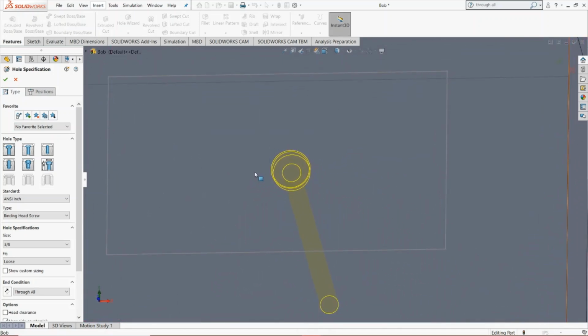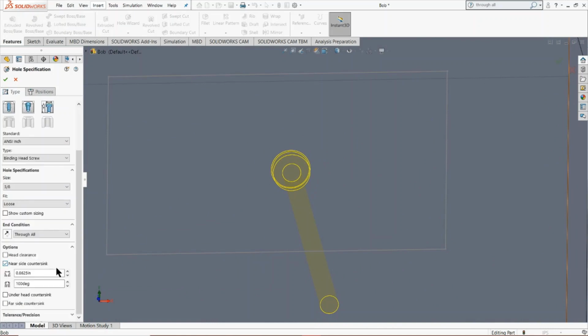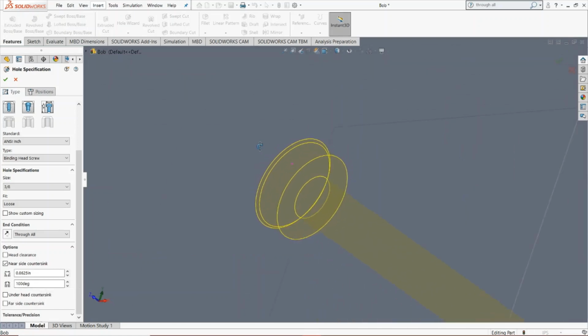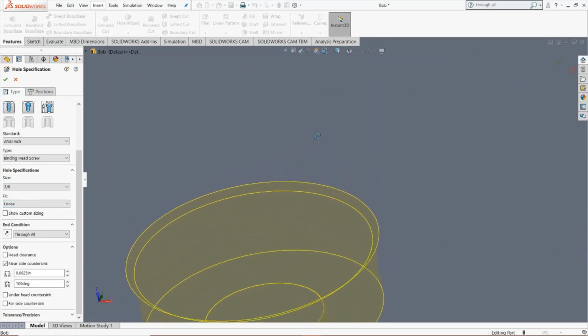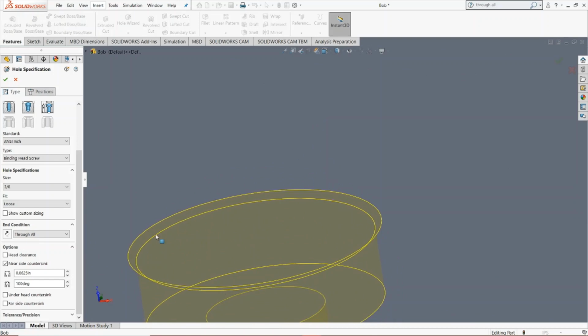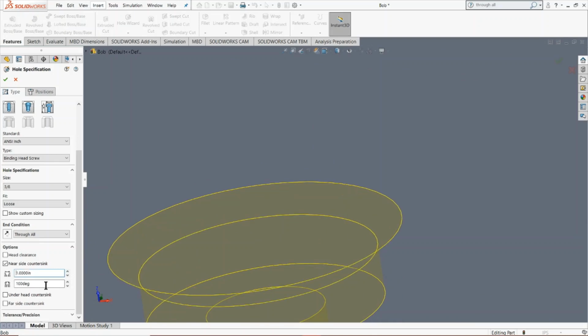Furthermore, you can see that we also have countersink values we can augment as well as the countersink angle. So if you're not familiar with countersink, essentially what that is is sort of the outline of where your screw is going to be. So if you can imagine drilling into a big piece of wood, for instance, you're going to be using a wood screw. It's got a triangular tip, and the countersink is essentially that offset value. So in this case, it's this angular component to this screw. So if I want to change our countersink diameter, we can do that. If we want to change the angle, we can do that.